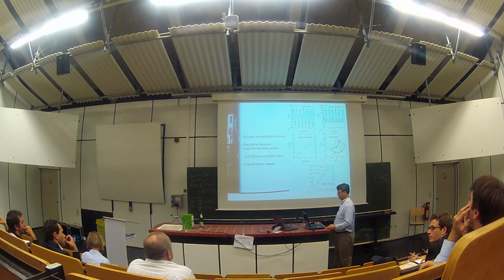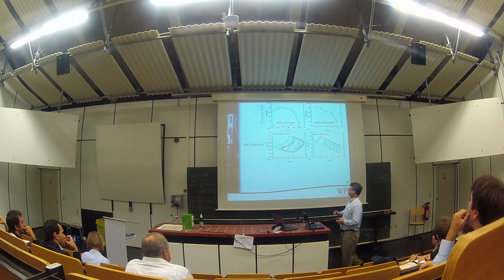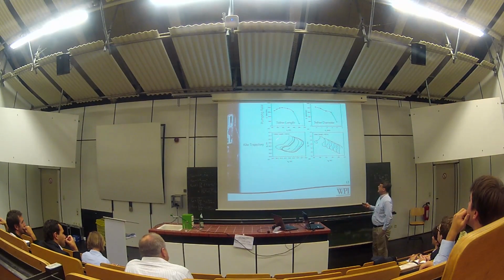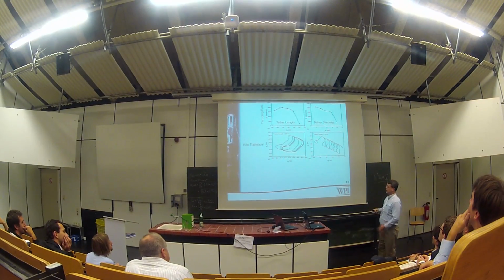All right, and for some of the key ideas, we did some design studies. Here is pumping rate, which is predicted, versus tether length versus tether diameter. And we do see these fall-offs. If tether length gets too high, or diameter gets too high, our tether drag takes over. So we have a sweet spot, so to speak, kind of similar for yo-yo and pumping.